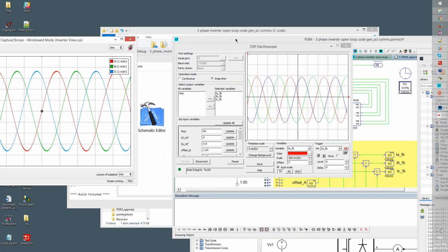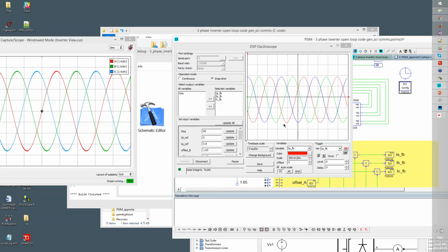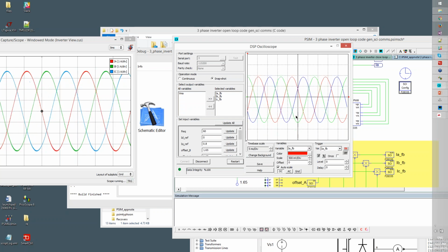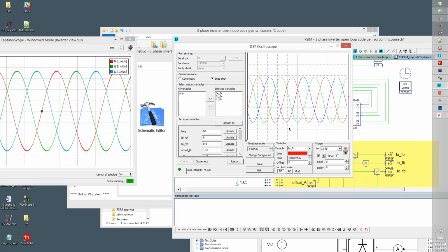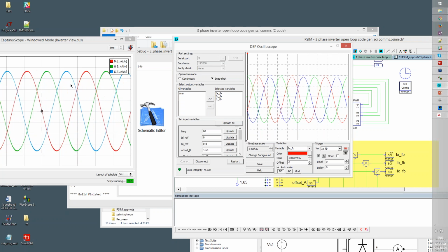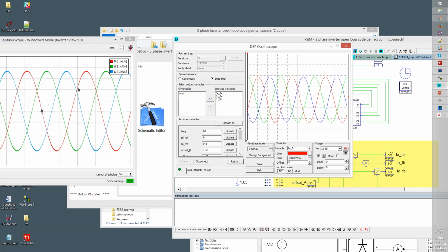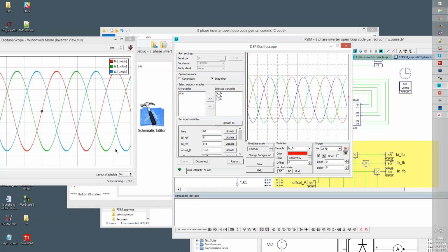But we can see that on this side, this is not set up. We're offset, as in, if we look, let me just pause it. We've got 500 millivolts per division, so we're just under 1 volt peak here, and then we're over 2 volts peak on the negative side, so our offset isn't set up properly, and our scaling isn't matching what the DSP is giving us, in terms of real numbers.